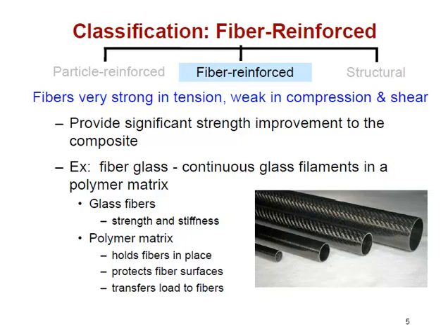But we don't necessarily want them approaching the limits of their bend radius in service, and so by using a matrix to fix them in position, we ensure that they are loaded in their strong orientation and their tensile orientation in the service environment within the material that we're manufacturing. So that's one of the big roles of the matrix, in addition to preventing scratching and just basically keeping the whole subcomponent together.